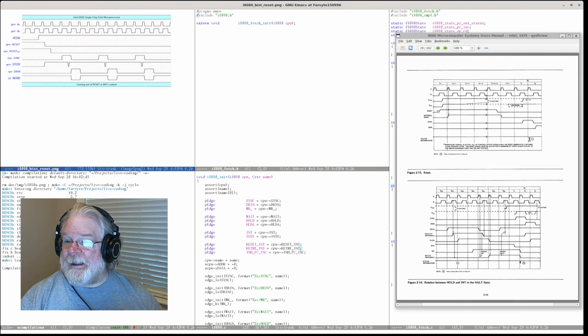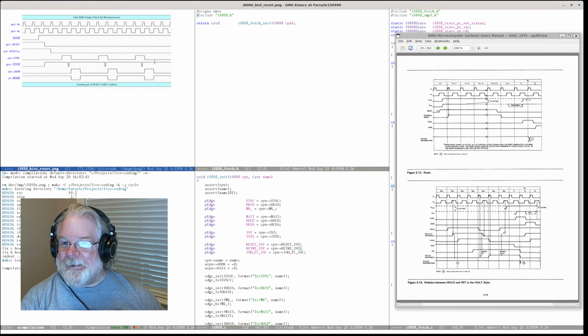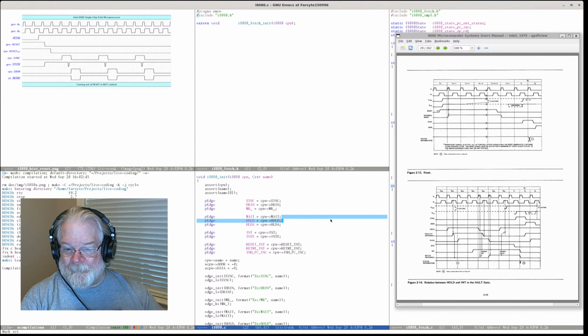And then, oh, looky here. We have a M1 cycle starting right here. Status strobe, and we do a fetch. And 4 cycles later, get another sync. So we are now off to the races. We are doing nothing. We're doing nothing with appropriate timing, which means that fetch is hooked up and reset is hooked up.